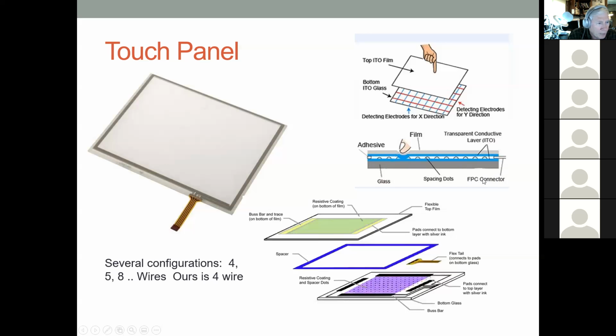They have a connector on the edges that works essentially as an electrode. So you can actually see the electrodes. These are these colored things here. And it looks like it's just a square, but they're broken up. You can see this one's connected to this wire and it goes up here. Then this one is connected to the next wire and it runs here. And this one runs all the way maybe to the edge and there's one at the top. So they do run around here and they are connected. Some are connected to the top panel, some are connected to the bottom panel.